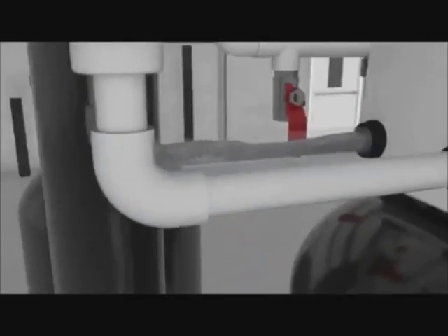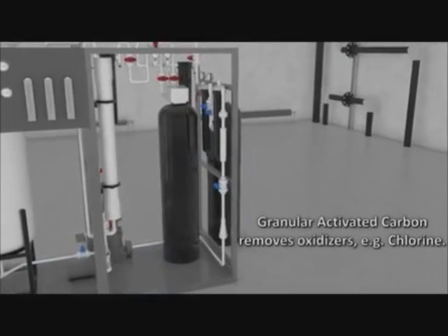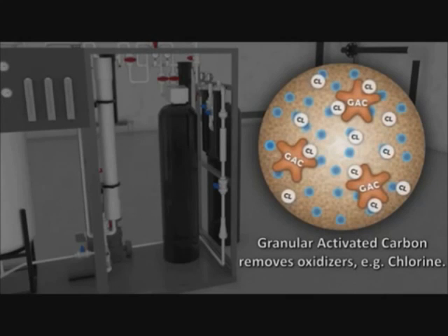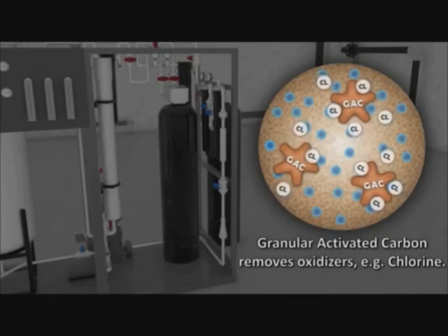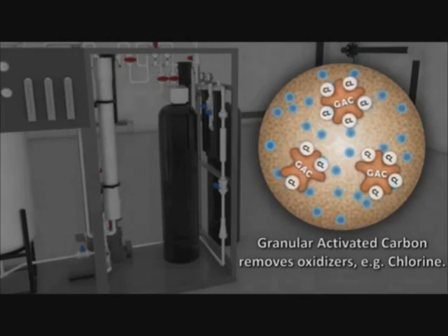Reverse osmosis is sensitive to oxidizers such as chlorine, typically found in all city water sources. Therefore, the process and water RO water system includes granular activated carbon, commonly called GAC. The GAC is an absorbent and will reduce the levels of chlorine being sent to the RO membranes.